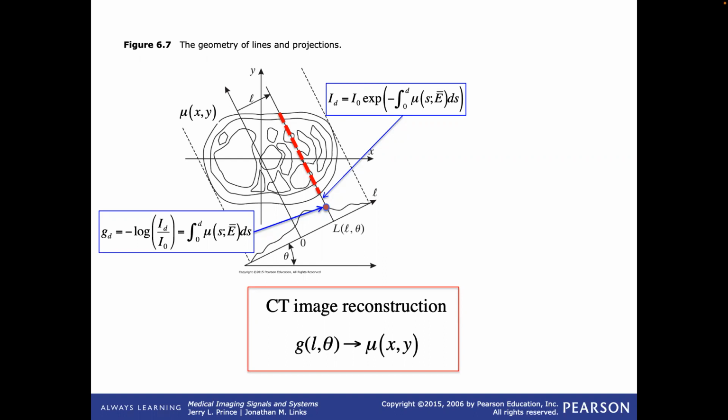And in that slice, which is like an axial slice, I have a two-dimensional function that is my data G(L, theta). And our job to reconstruct that data into a picture of the underlying object is to find the transformation from this to the linear attenuation coefficient as a function of X and Y. And then it'll look like somebody's heart in their chest, right? So this mapping,